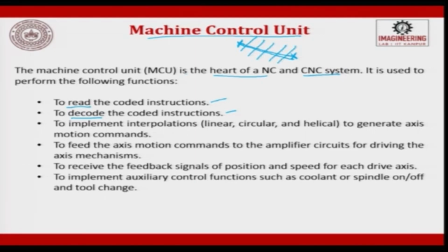Okay. So, linear is this, circular is this. I have given you the start point, the end point and the radius, and now I can find the intermediate points and do interpolation, which is circular interpolation. And the third one is helical interpolation, which is nothing but linear plus circular, which leads to a helical.